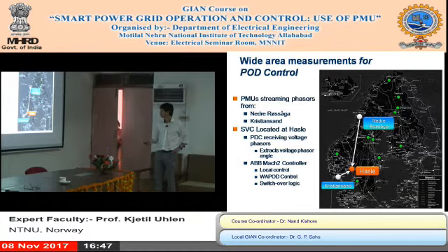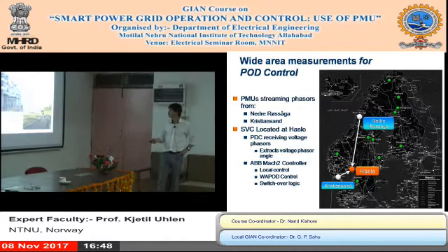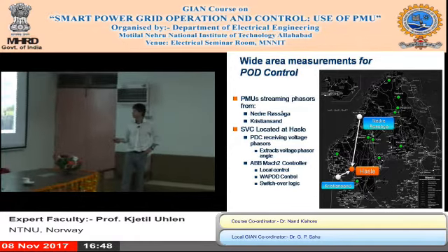This was all implemented in ABB's state-of-the-art controller at that time, with the local control, with the wide area POD, and with a switch over logic that I will explain. If you wonder how a thyristor controlled reactor looks like, this is the picture of the reactors.